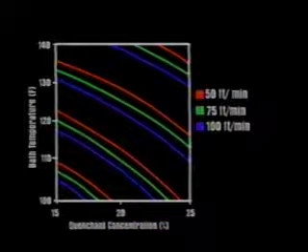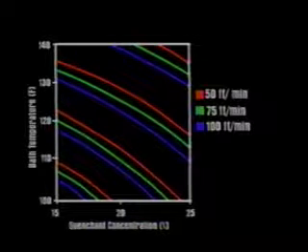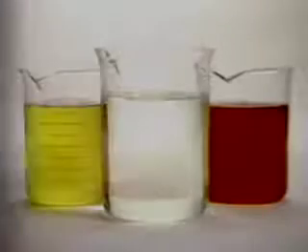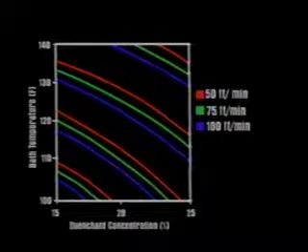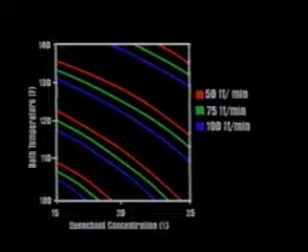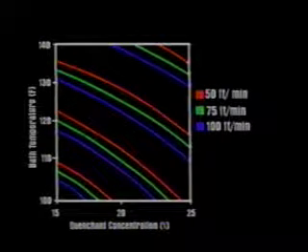A temperature rise during quenching in oil is not so critical, as quenching severity in oil is less affected by temperature. The second reason is that thermal gradients around the part will greatly increase the potential for increased distortion or cracking. For polymer quenchants, the effect of quenchant concentration is also important. This plot shows that increasing quenchant concentration will decrease quench severity. This is reasonable since high polymer concentrations provide greater insulating film thickness and slower cooling rates.